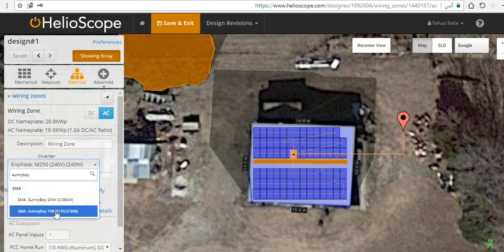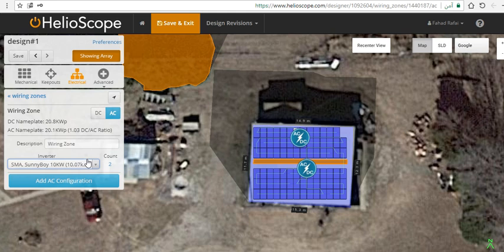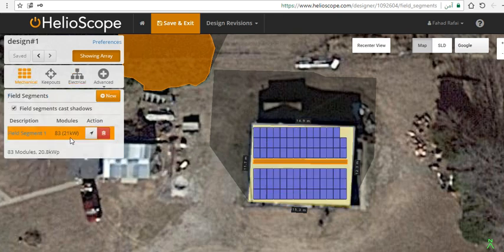here we have 2 kilo and 10 kilowatt. So if you choose 10 kilowatt, in this case, the program will tell you that you need 2 of this inverter. Why is this? Because this is only 10. So 2 times 10, the total will be 20 kilowatt, or almost more than 20 kilowatt, because our panels is 21 kilowatt.